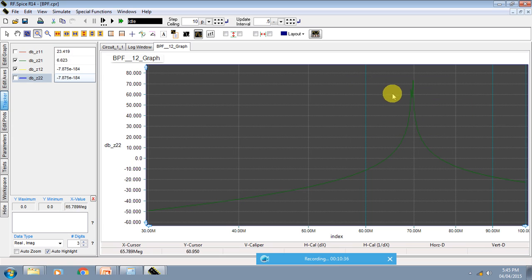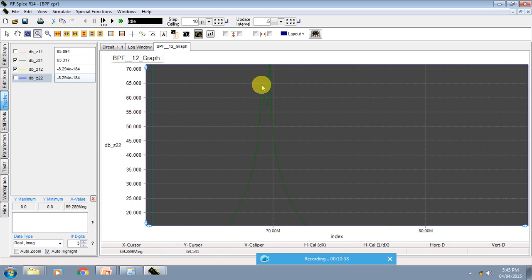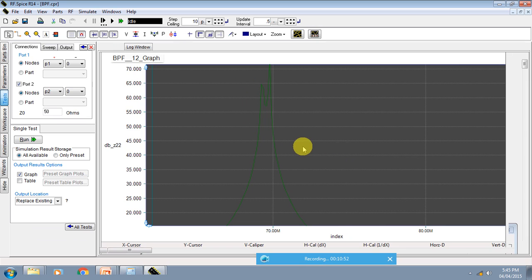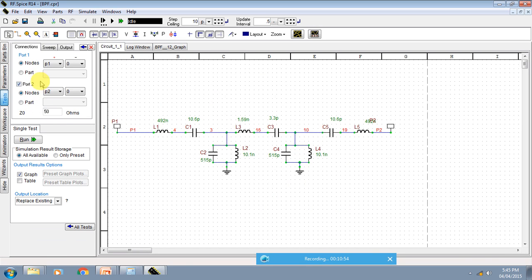So here one dip is coming, and this is actually the Z parameter variation handled by your filter. This is the natural graph of the impedance trends, shown by this plot. Even in the next plot, for the output side, you can see the real and imaginary, and the Cartesian Y parameter. S, Y and Z parameters you can observe.